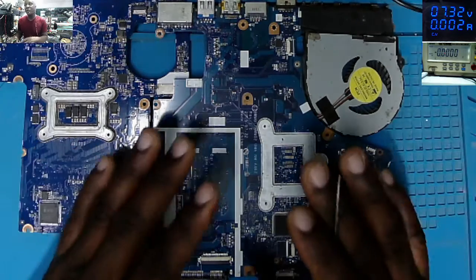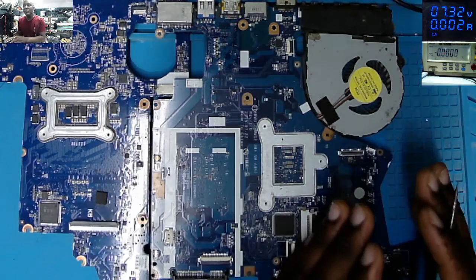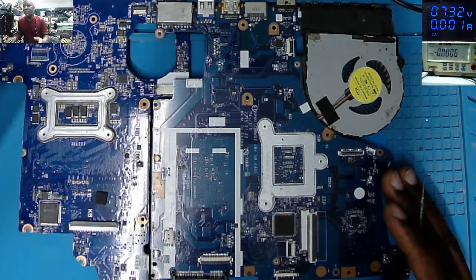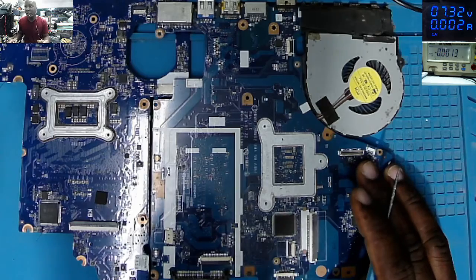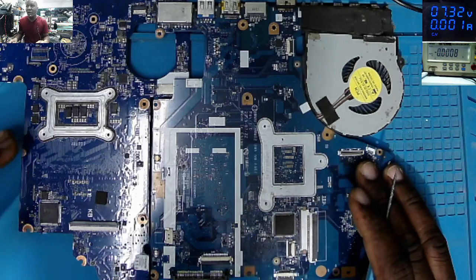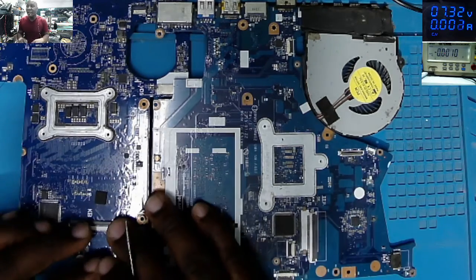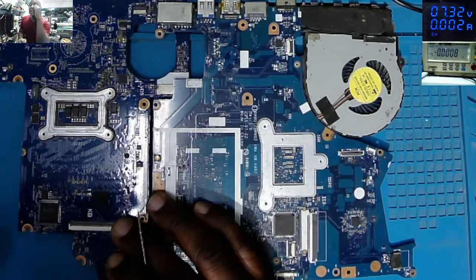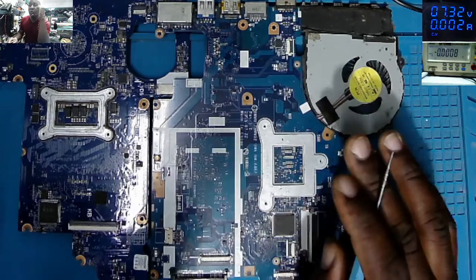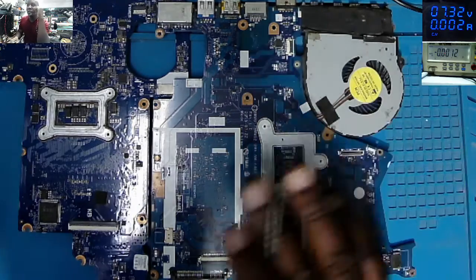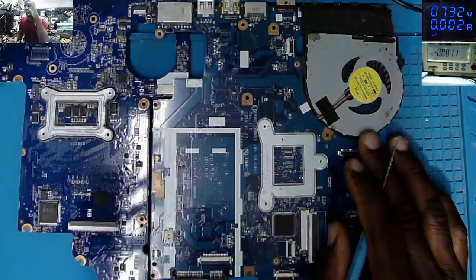And obviously on the charging port we have the two MOSFETs in serial mode, the current sensor, and from the current sensor, that's the VCC point of the main 19 volts power line. From that current sensor, the 19 volts is going everywhere. It's going to 3.3, it's going to 5 volts, 1 volts, 1.5 volts, all over the motherboard.